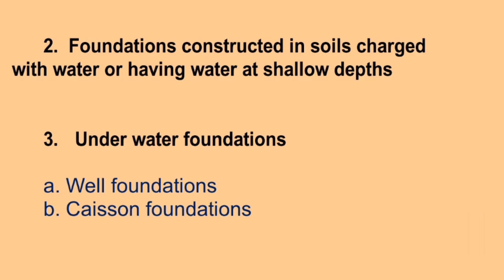Second one, foundation constructed in soils charged with water or having water at shallow depths. Third one, underwater foundations. The bridge foundations constructed underwater are known as underwater foundations. These foundations are considered as deep foundations. Underwater foundations are further classified into the following two types: well foundations and caissons foundations.